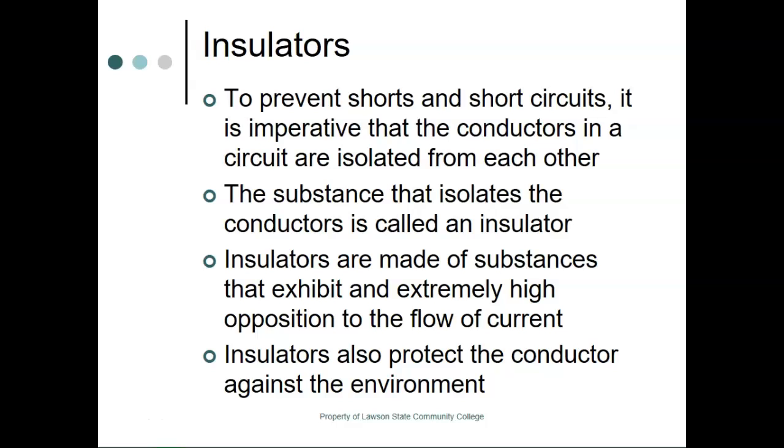All right, so insulators. To prevent shorts and short circuits, we take conductors and isolate them from themselves. This is why every time you look at any kind of a cord or cable, if you look inside them, with the really big ones, they have bundles of cable. But I digress. So we try and keep source conductors away from each other. Source and returns should never come in contact. If they're even touching each other, they need to have a bunch of insulation between the two so you don't end up with arc over.